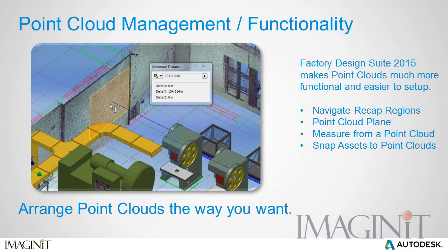The 2015 release of Autodesk Factory Design Suite makes point clouds much more functional and easier to set up. New commands include the ability to navigate Recap regions inside of Inventor. You can now easily create a point cloud plane, and you can measure from a point cloud plane to any given asset. You can also snap assets to point clouds.